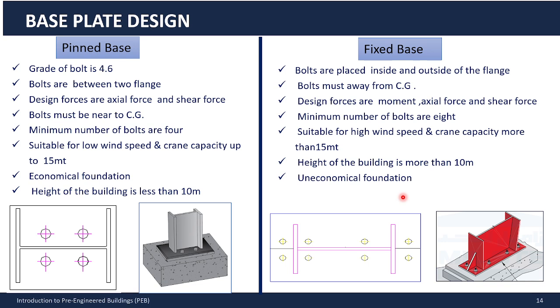It is economical. A fixed base uses bolts inside and outside the flanges and resists moment, axial and shear forces, and that needs a minimum of 8 bolts and is used for tall buildings or high wind and crane loads. It requires a heavier, more expensive foundation.